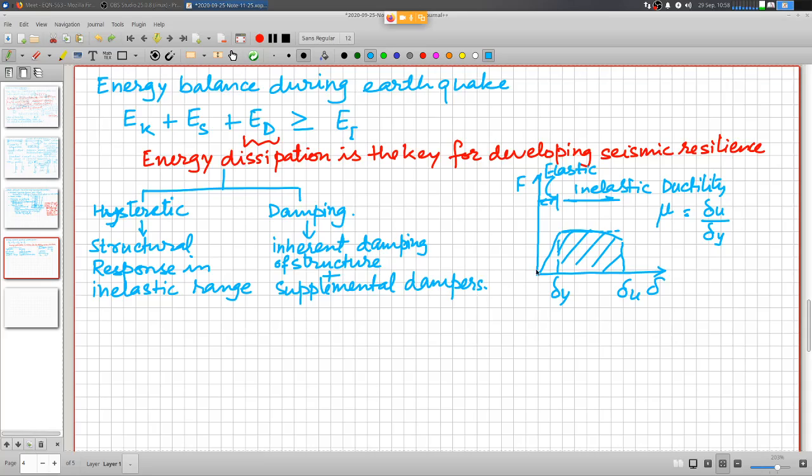And then there can be several things, for example, let's say reinforced concrete. How do I make reinforced concrete behave like a ductile material? Most of the time you will find reinforced concrete would have just a very small yield and then immediately drop off, right? So this is brittle, and this is ductile.